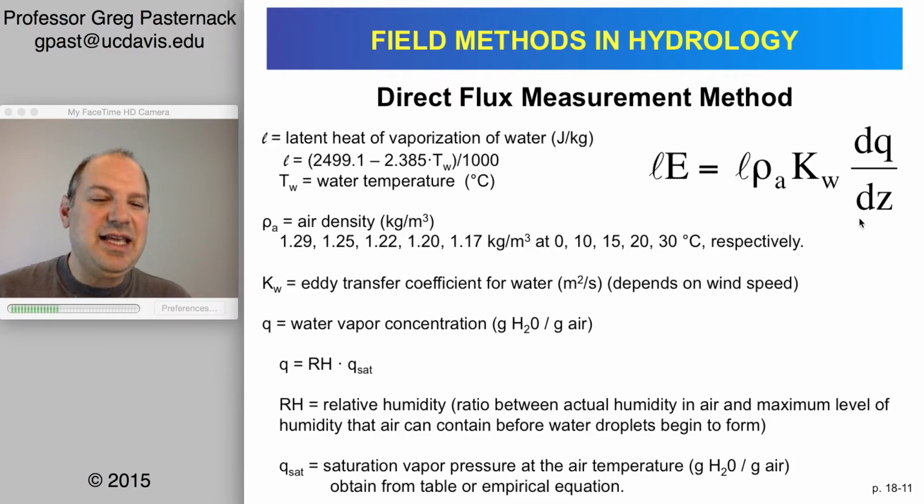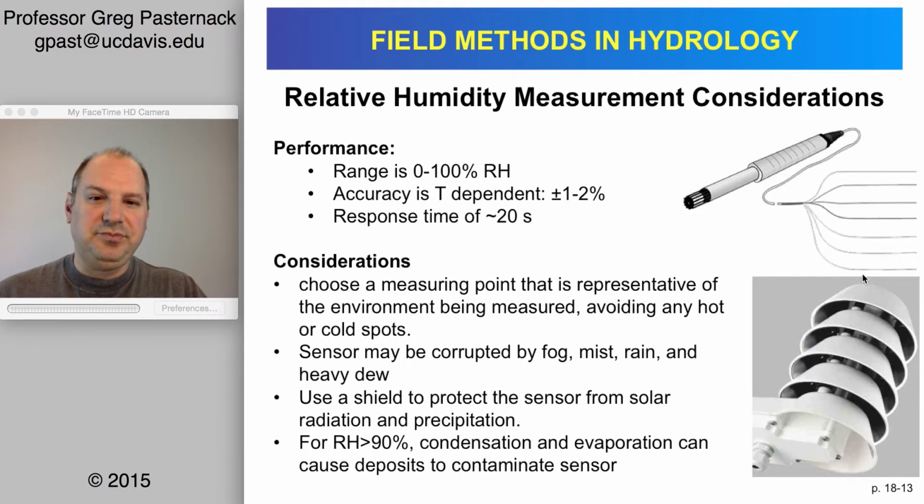It's easy to get scared by the fact that you're seeing an equation, but so much of flux is just like this. It's not even that different from Manning's equation. Again, flux is proportional to the slope of the water surface times some indicator of velocity, which could be Manning's n, and you have your water depth. There are basically all the same kinds of equations. They're flux equations. They're used extensively in physical science, and you have to become comfortable with those.